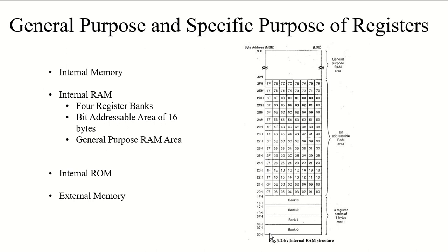But there is one more thing which you have to always be careful about: whenever you turn on the power or reset the microcontroller, bank 0 will be selected by default, right? So you have to deselect it if you want to use this area as a scratch pad. So always remember that.